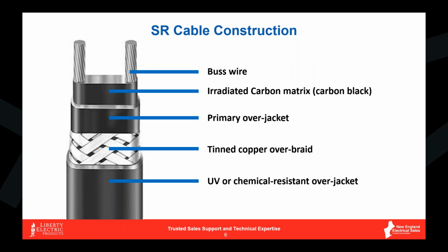And originally, when these cables were first put into commercial and industrial use, they were designed with just the primary overjacket. These were very popular for doing water piping for trailers, and some of these structures were almost temporary, where we just got to put a little bit of pipe tracing on this thing to keep it from freezing over the winter time. And basically what was happening during the product's inception was that you get animals or critters in there chewing on that cable, and with no grounding, you could light things up. I mean, there was no GFI code requirement at that point in time.